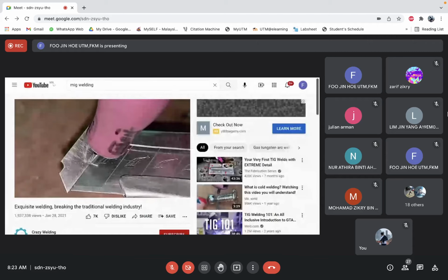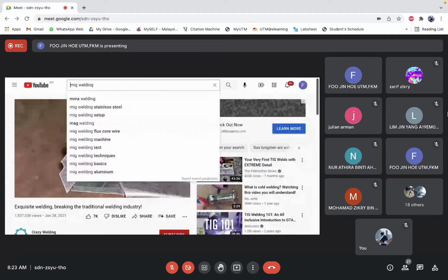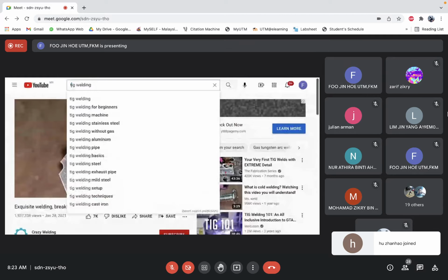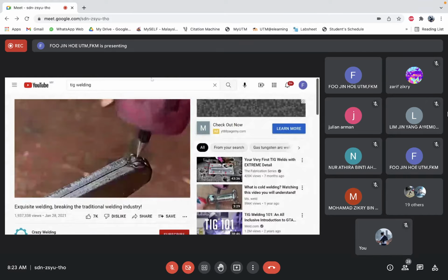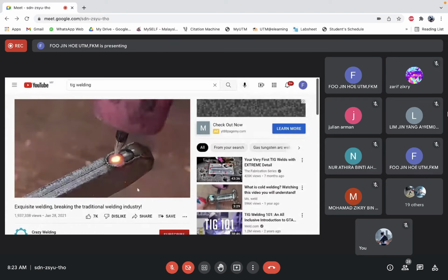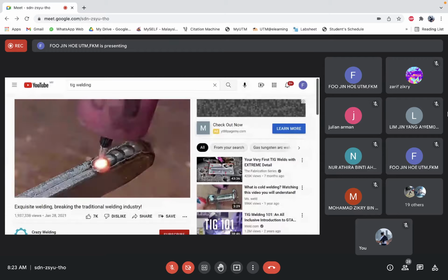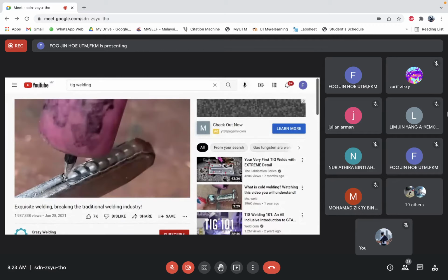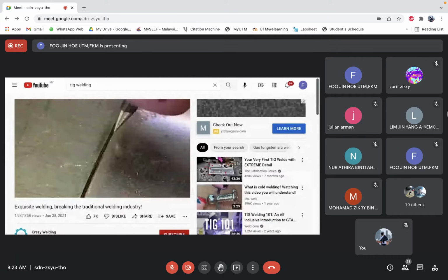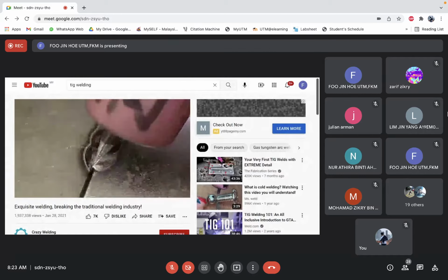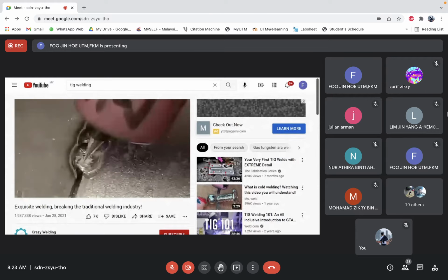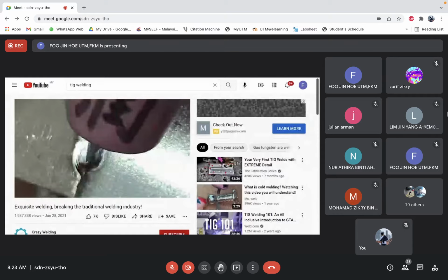Pay attention to thermal conductivity, electrical conductivity, melting point, and other properties of the base material. For metal materials with high thermal conductivity, welding methods with large heat input and strong penetration ability should be selected. For heat-sensitive materials, welding methods with low heat input are easy to use.